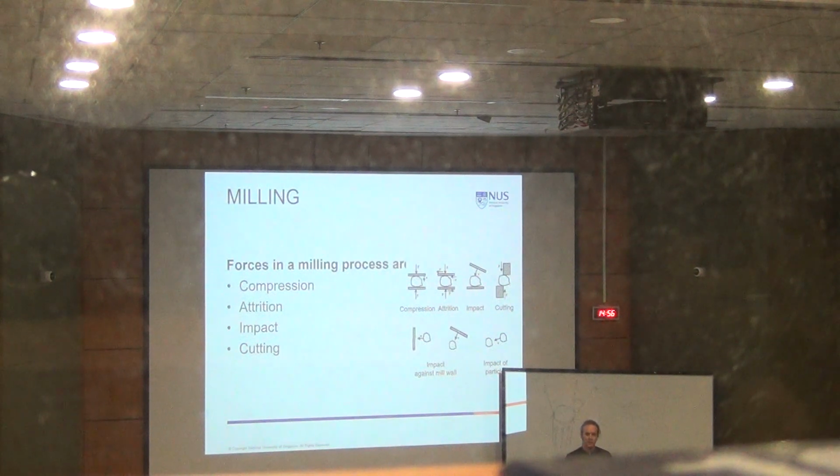For example, when you think about the ball mill, then you will automatically understand that it makes sense that very often you also get impurities in your powder, because when you mill something by friction, you have surfaces involved. It is also automatically clear that you have heat generation in this mill, because of this basic principle applied in the grinding process. You also have a certain amount of impact, but the focus of this mill is really attrition, that you have in the end a lot of friction in this mill, which leads to grinding.